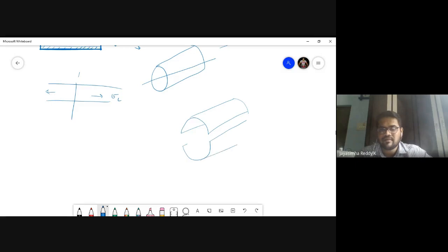Alright, is it clear, students? So it will break down like this, whereas this is circumferential. There will be application of force like this, everywhere, and because of this pressure there will be circumferential failure. To stop this from failing, there will be stress offered by the material, that I am calling circumferential stress.